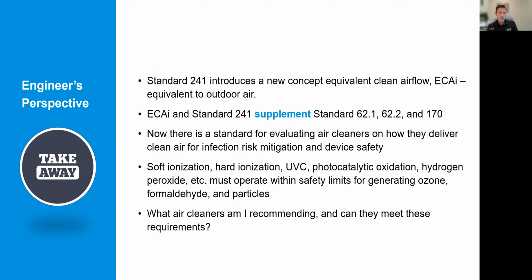Now, under the standard, there's a way to evaluate air cleaners for how well they work and how safe they are, meaning that they don't generate byproducts. In the scope of the standard are soft ionization, hard ionization, UVC, photocatalytic oxidation, and all of these other air cleaning technologies, which must operate within the safety limits. Those safety limits are how much particle they generate, how much ozone they generate, and how much formaldehyde they create. So those are the three safety byproducts that are tested. And basically, the quick takeaway I'm going to ask all of you is, as you recommend air cleaners, what are you recommending, and do they meet these requirements?